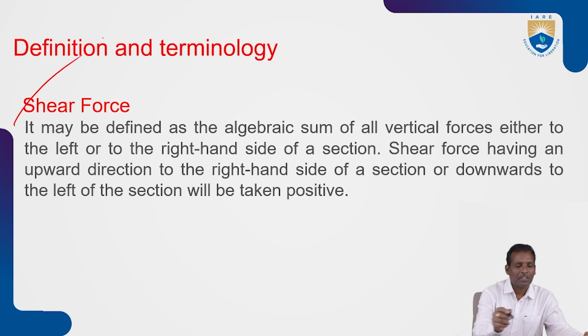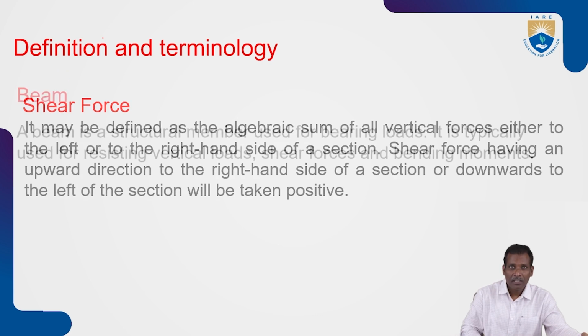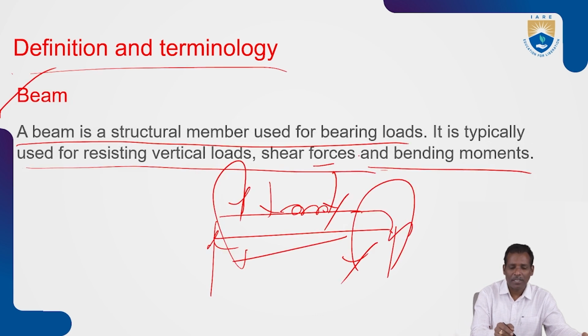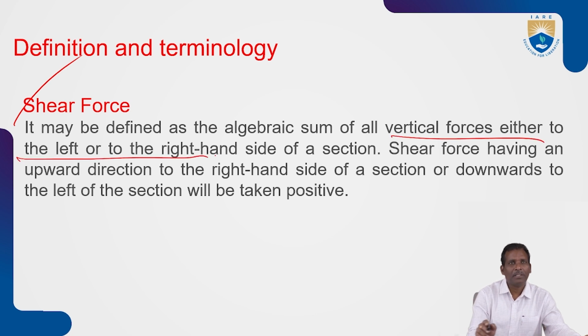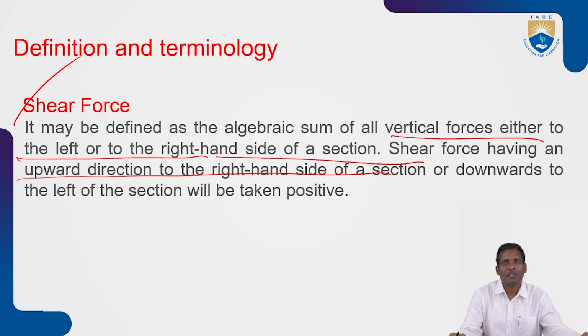Now coming to the shear force: what do you mean by shear force? Here, the term shear force and bending moment is used. Shear force may be defined as the algebraic sum of all vertical forces, either to the left or to the right hand side of the section. Shear force having an upward direction to the right hand side of a section, or downwards to the left of the section, will be taken positive.